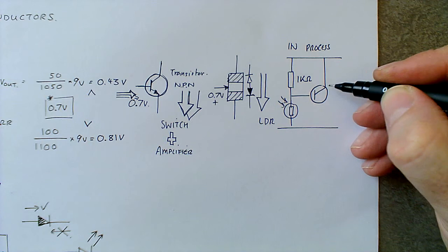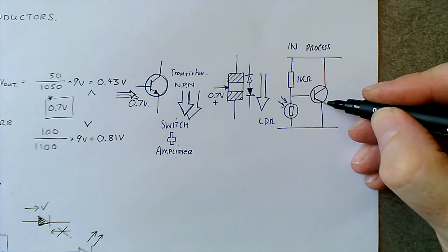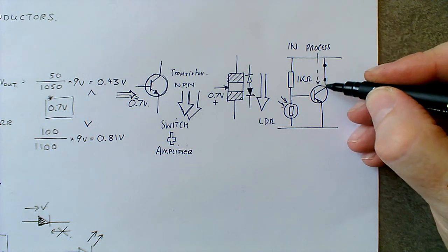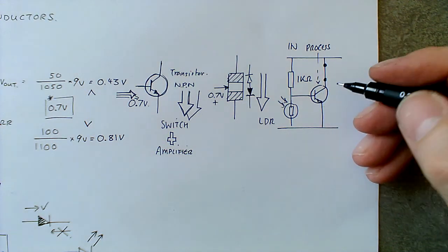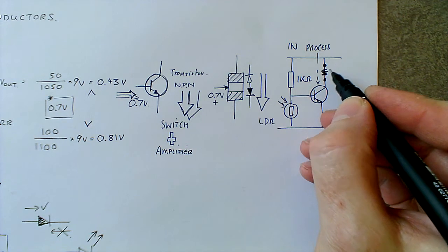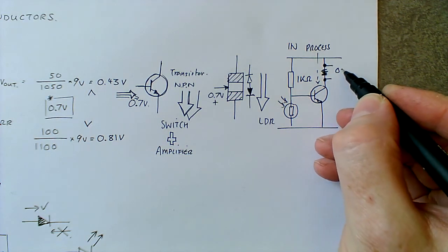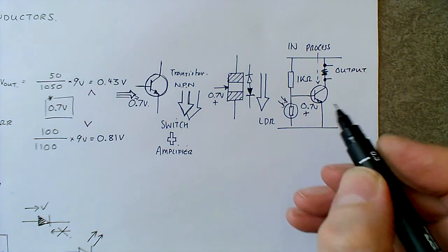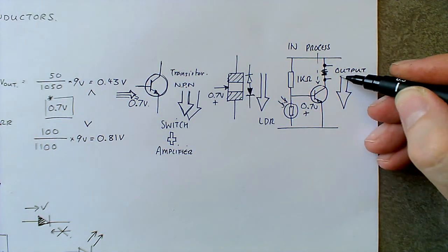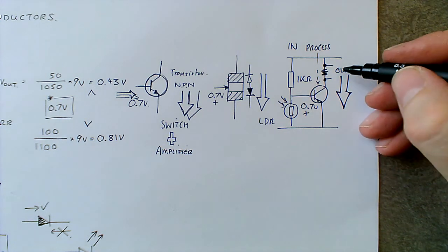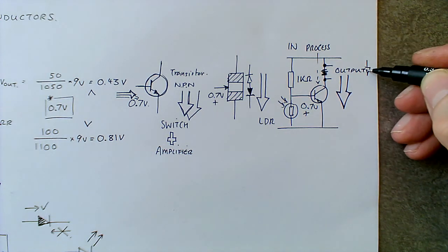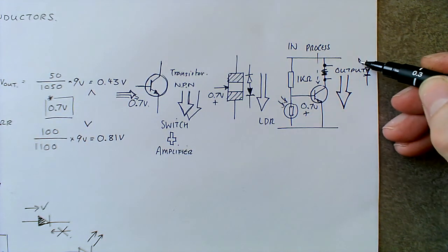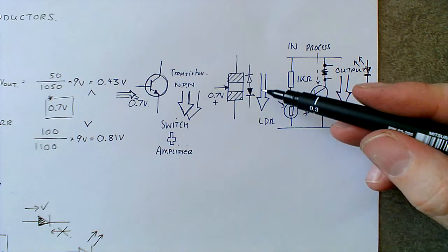So there's some sort of process happening whereby, I've just overdrawn the lines, I wanted to put something in there. Our process is the transistor, so when it receives its threshold voltage we can get, so if you can just ignore that bit there, we can have an output, because we'd have a small voltage here, 0.7 volts plus will mean that we'll get a larger voltage here. So for example we could put an LED there, and when the switch is activated here the LED would light up.